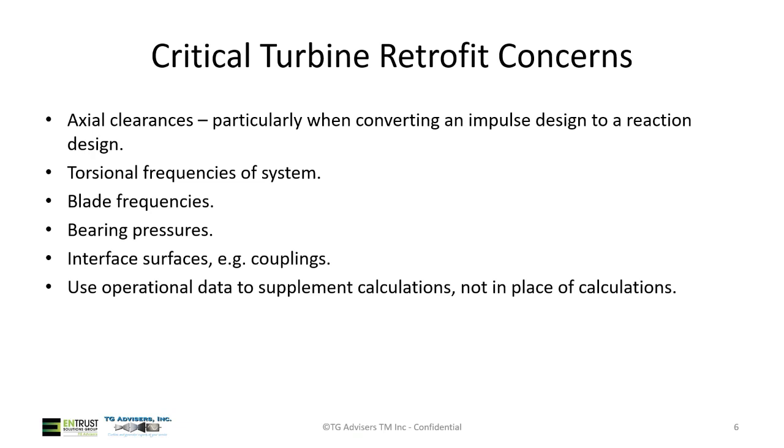Interface surfaces, you have to consider, you're adding a new rotor, so make sure that everything's properly engineered for the coupling interfaces and existing components that are not being replaced. And then also a key one: don't rely fully on operational data to supplement things in place of calculations. Make sure all the calculations are done and review the design process with the selected OEM or manufacturer.